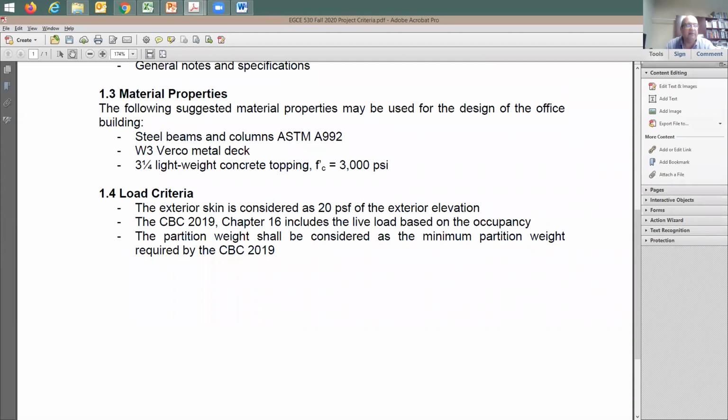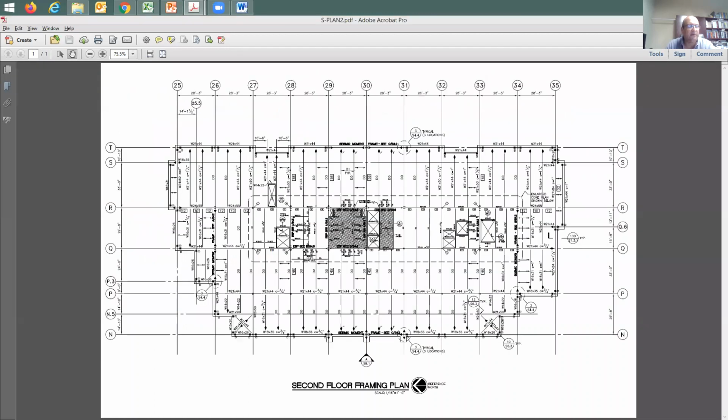First, let's look at the plan, try to understand it, and see what's going on there. Here's a plan view. We have a bunch of grid lines running in the, I'm going to say this is giving the north-south, and this is giving the east-west. The reason is because if you look here at this symbol, this is giving the north direction. So north is this way. So this gives you the grid lines in the north-south, and this gives you the grid lines in the east-west.